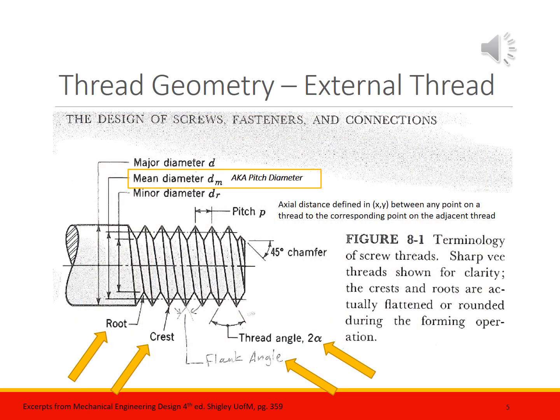The thread pitch is defined as the axial distance between a point on the thread corresponding to the same point on an adjacent thread. Manufacturing variation aside, the dimensioning and tolerancing of thread form is based upon the ideal. Gauges, however, will check reality.